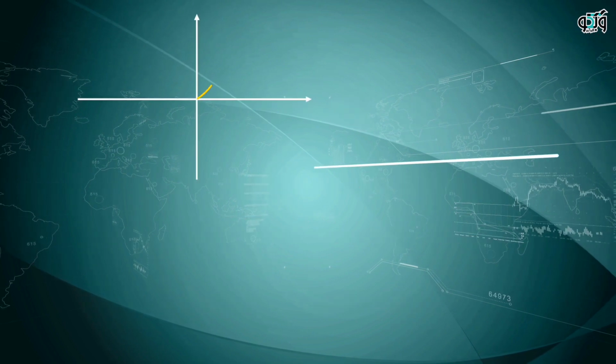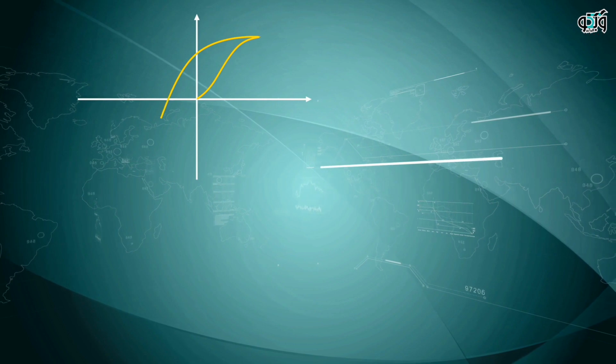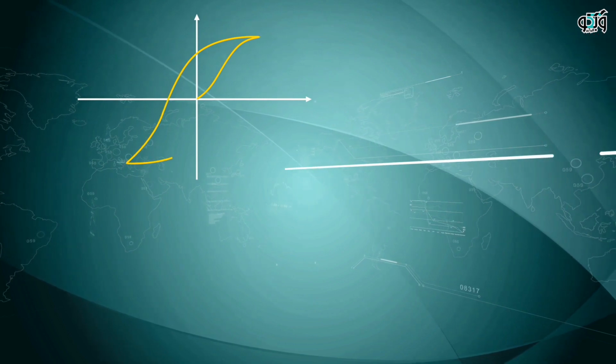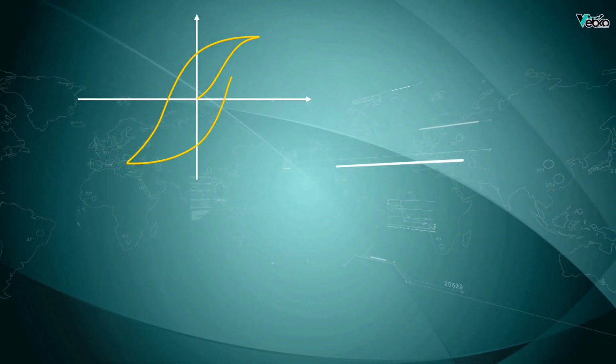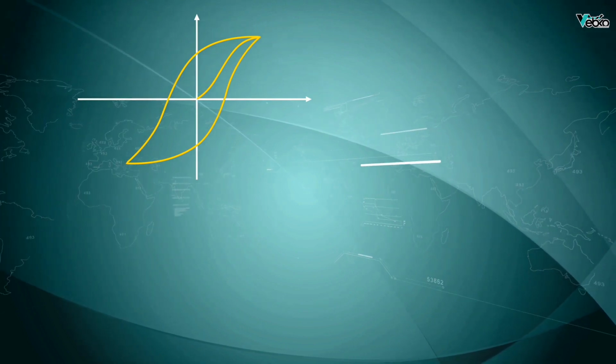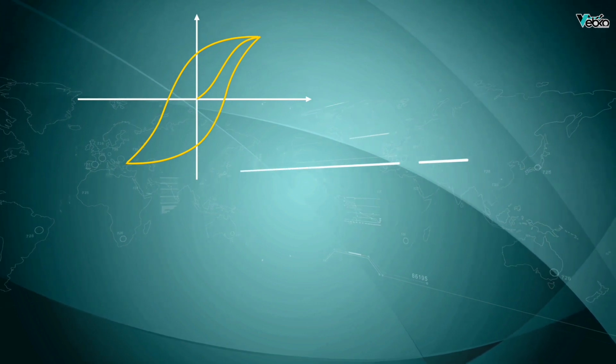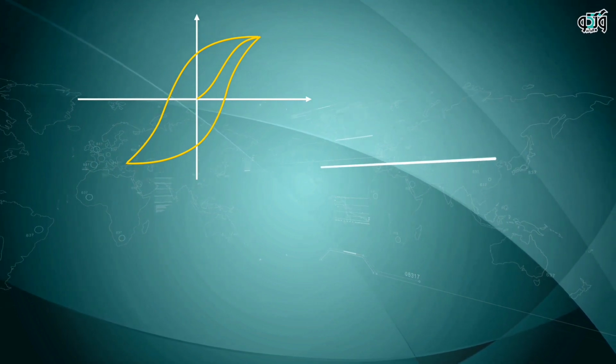Hysteresis losses occur in the core due to the residual magnetism. This means that the passing of the magnetic flux through the metal core in a direction causes the core to be magnetized and turn into a weak magnet. So in the next half cycle, a small amount of energy is lost to remove the magnetic effect of the previous half cycle, and this is constantly repeated.